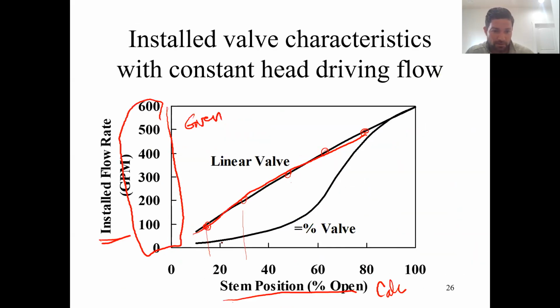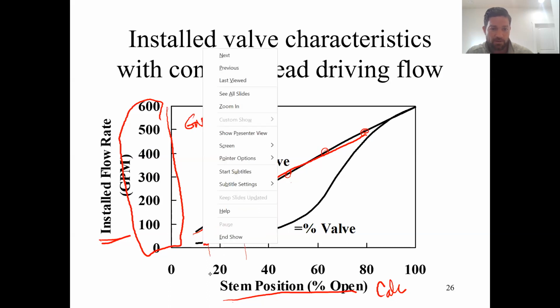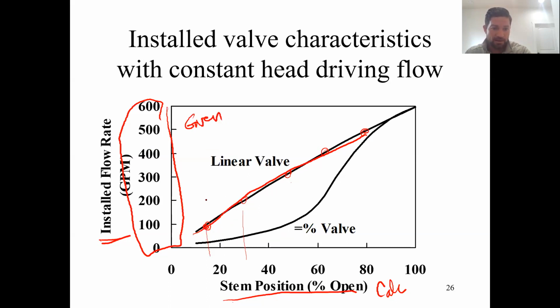So we did that here also, right? So here's now we're looking at, going back here. So again, at 100, well, we would have to use different increments here. So if we used 100, we would have calculated this for equal percentage, same size body. 200, it would show up here, 300. And so maybe we might have to go down and do a calculation for 50 to get these points down here. So what you see now for an equal percentage, the shape of the curve is going to look like this. It's going to open a little bit at slow flows, and then it's going to open a lot at higher flows.